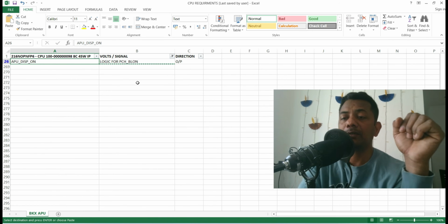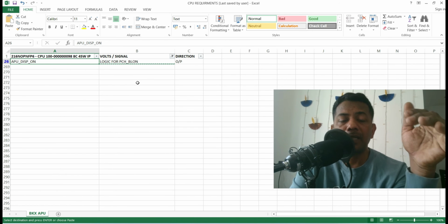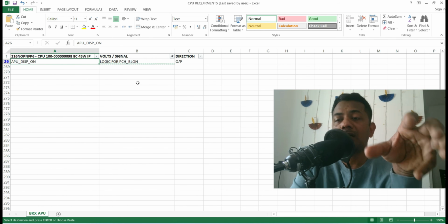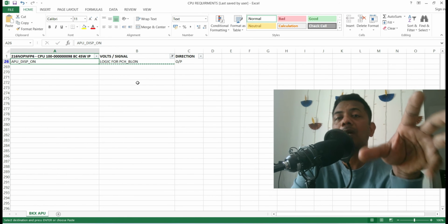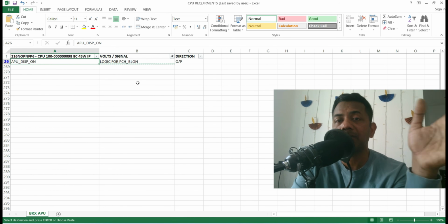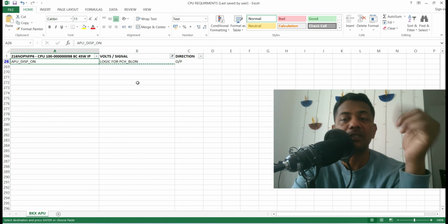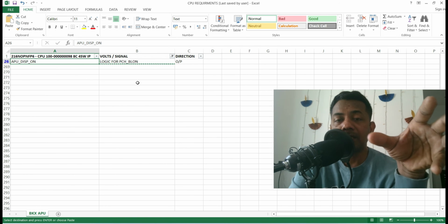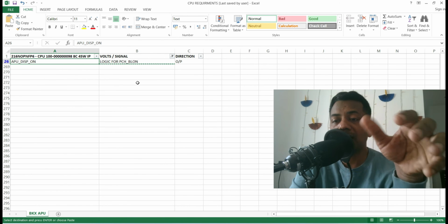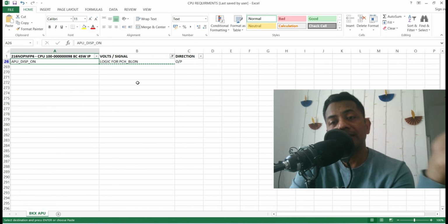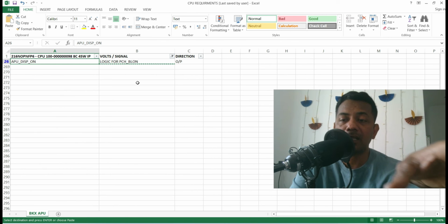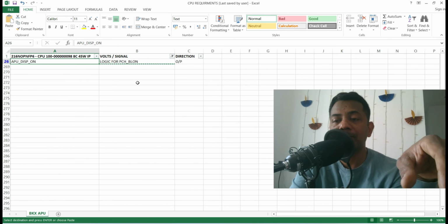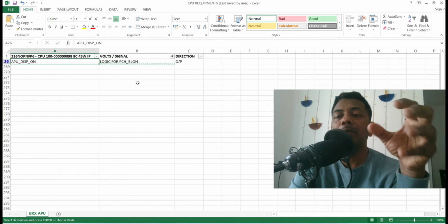See, one thing you come to know: the main CPU or APU or SOC or PCH, whatever it may be, all have blocks. What are those blocks? Already explained in multiple videos, please go ahead with those videos. And here again and again I am mentioning: if a particular block is not receiving any signals, or inside only it has a fault, then we can consider it a faulty APU or CPU or PCH, whatever it may be. Please don't judge blindly.